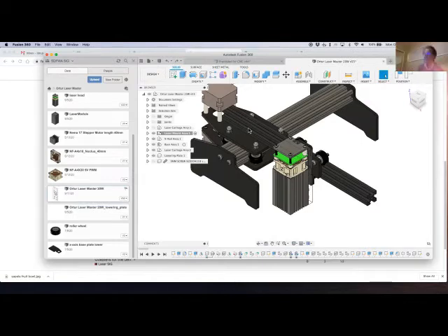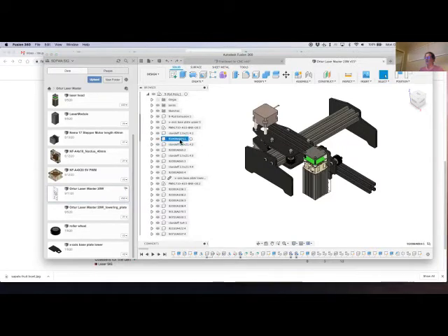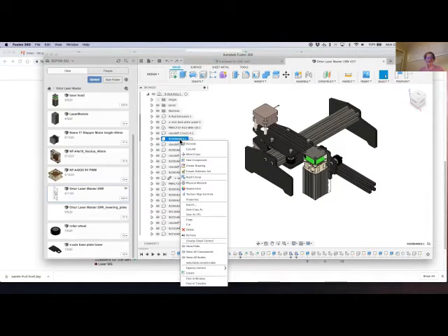The main point I wanted to make here wasn't even the more complicated assemblies, but it was being aware of what level is activated when you're trying to do things. And if you've activated the wrong thing, if you've activated this assembly, but meanwhile you come down to this assembly and you try and copy paste something, where's it going to end up?